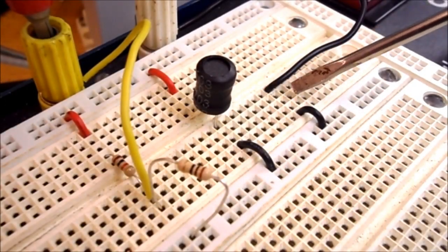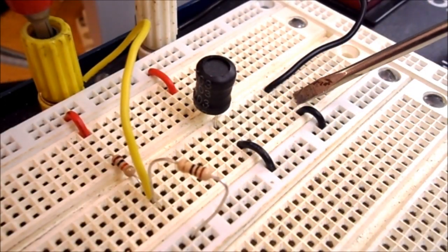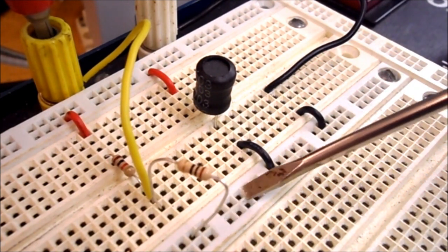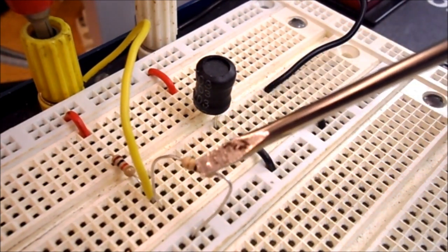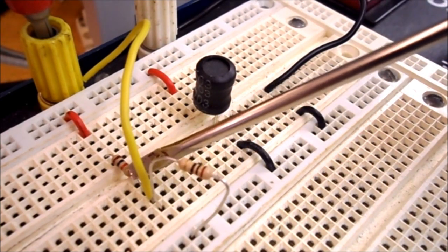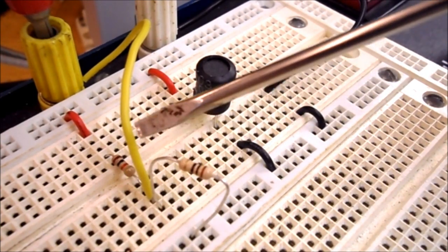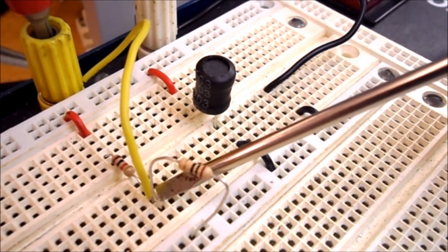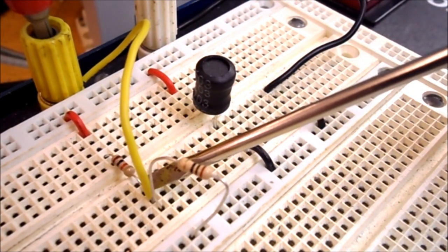I've now replaced my sensing resistor with a little short jumper, so that now brings in ground to the entire ground bus. And I've put my sensing resistor in series with my 1K ohm resistor and moved channel 2 to see the point between the 10 ohm resistor and the 1K resistor.